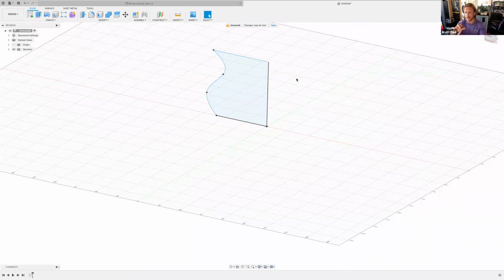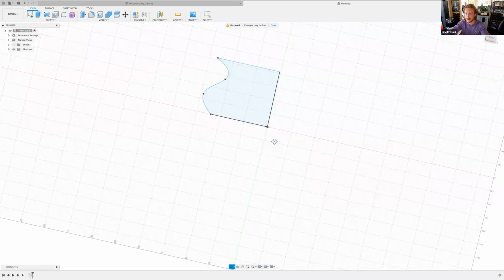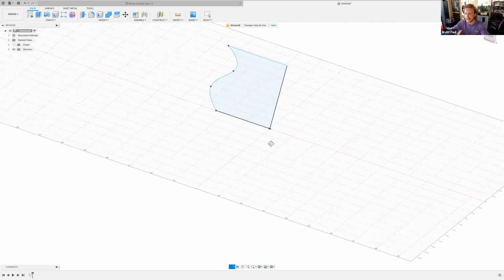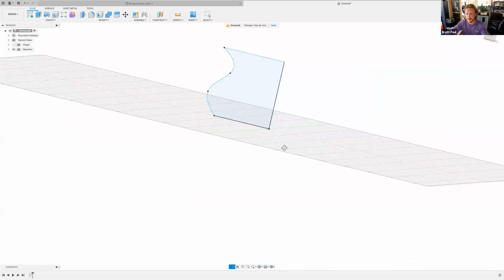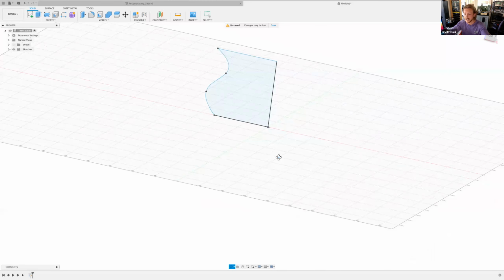If you're on a laptop, I don't know what that equates to. But if you are on a laptop and you want to get to an orthographic view, something you can do is go down here to orbit, okay, on the bottom panel, and that allows you to freely orbit as well. It's the same function, it's just not as quick. It's going to stay in orbit mode. Okay, I'm not going to get out of it until I click escape.